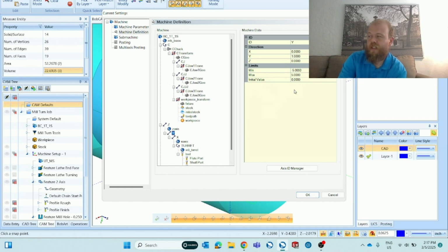I'm almost sure this is in inches, as long as you have it in inches down at the bottom right corner of your software program. But when you get errors of an over travel, that always comes up in millimeters. But here you can set it up in inch. Let's see, X-axis, we've got +/-30.